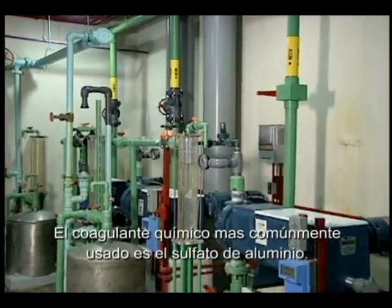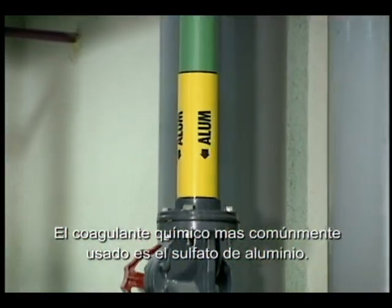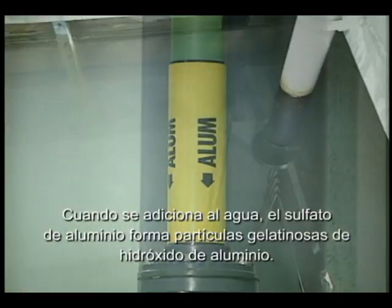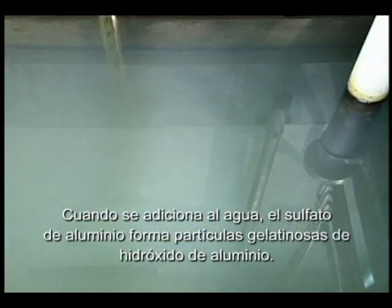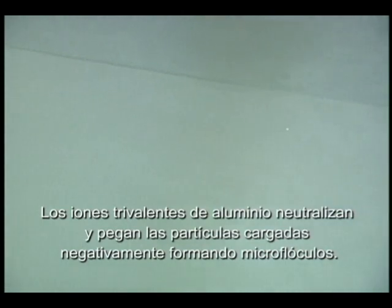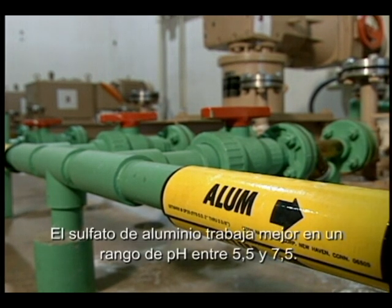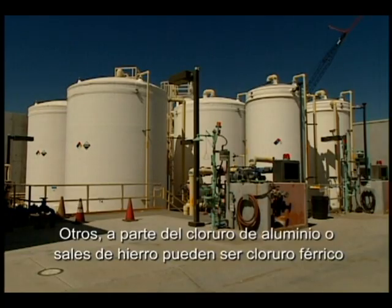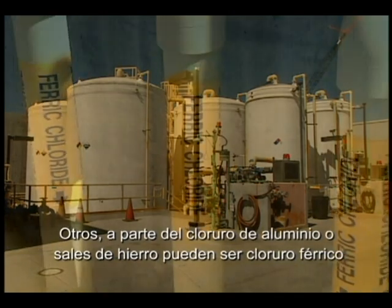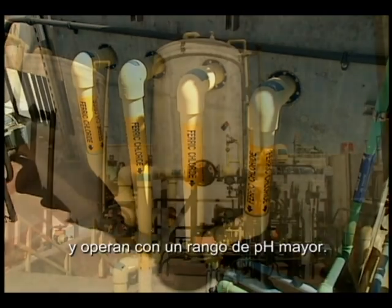The most common coagulant chemical used is aluminum sulfate, commonly called alum. When added to water, alum forms jelly-like particles of aluminum hydroxide. The trivalent aluminum ions neutralize and attach to negatively charged particles in water, forming microfloc. Alum works best in a pH range of 5.5 to 7.5. Polyaluminum chloride and iron salts such as ferric chloride and ferric sulfate are alternatives to alum, and they operate over a wider pH range.